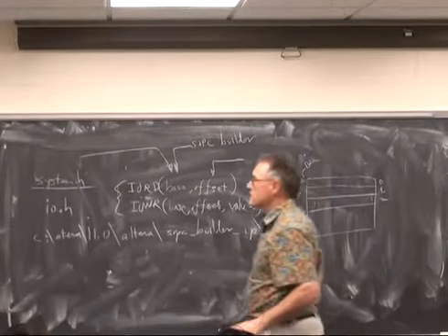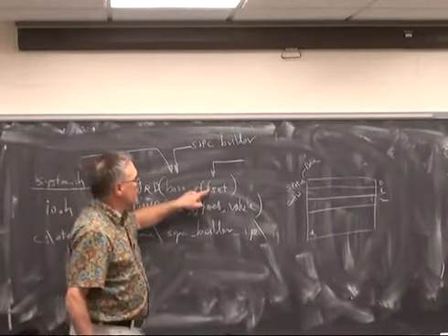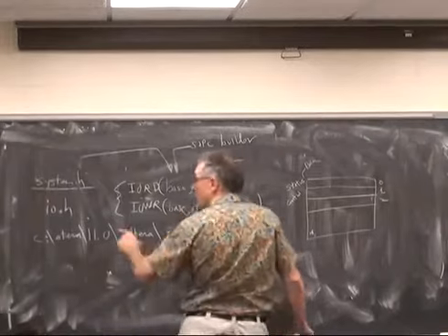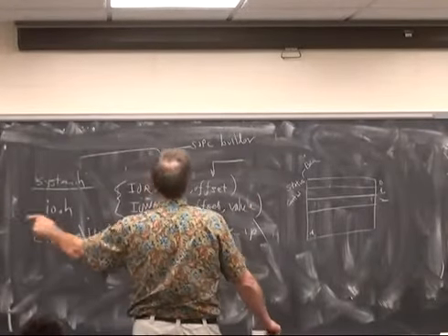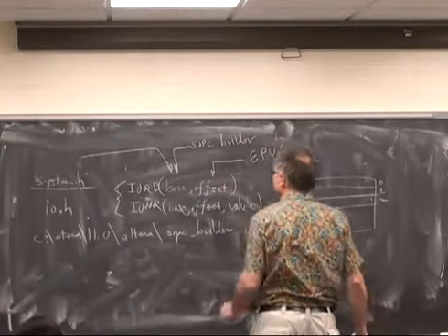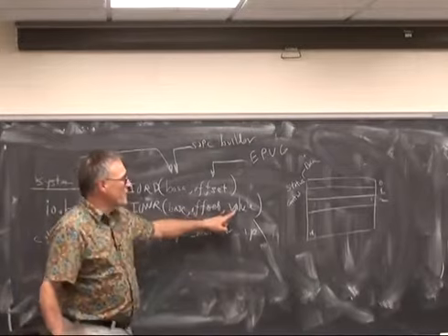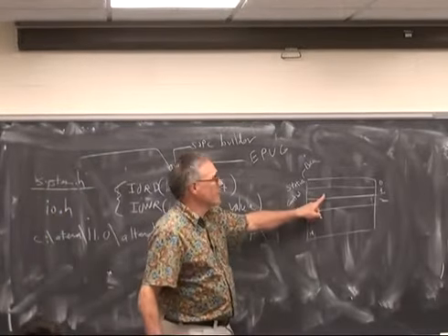So we specify the base from system.h, the offset from the Embedded Peripheral Users Guide, the EPUG, and the value, of course, is going to depend upon what is being defined in these fields.